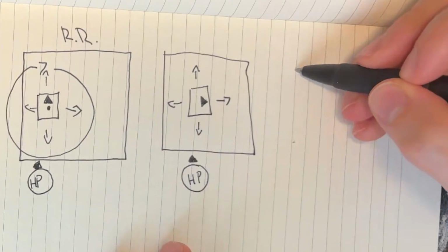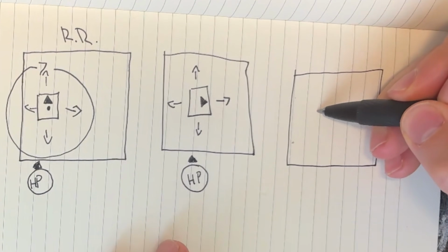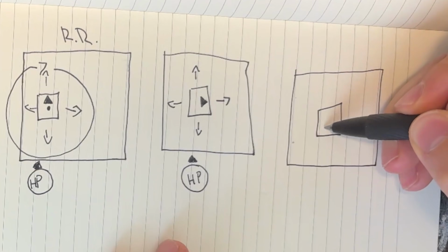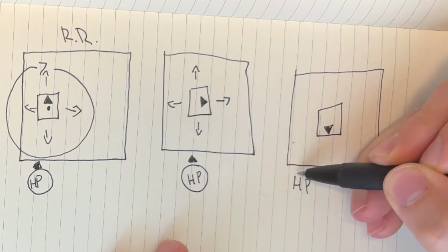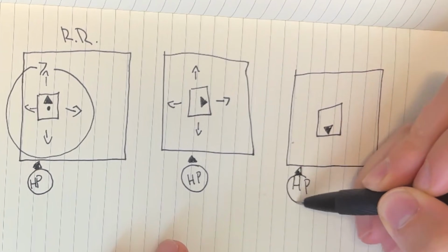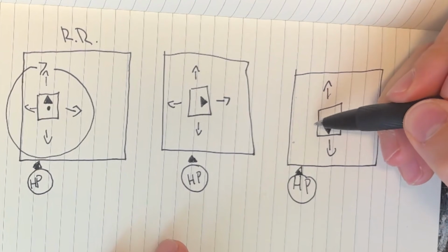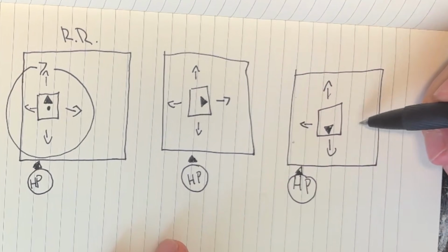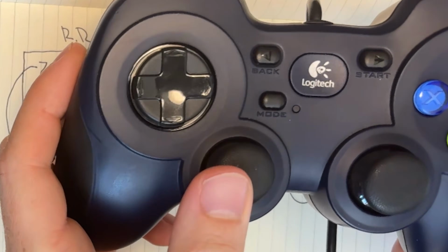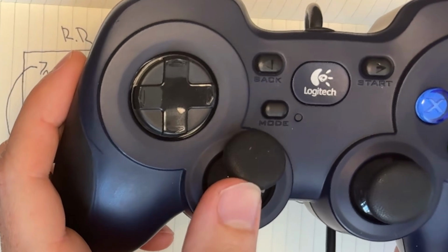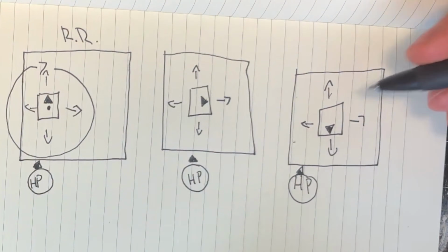Where this really starts to get confusing is if your robot is in the downward position, because now if you are still facing forwards, this is forward, this is reverse, this is right, and this is left, except that would move your robot right, that would move your robot left, move your robot down, and move your robot up relative to the field.